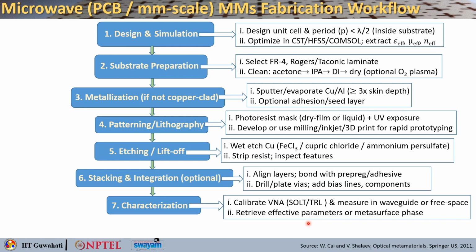And finally, you can analyze the S parameters, that is scattering parameters, to retrieve the effective parameters or the metasurface transmission or reflection phase.